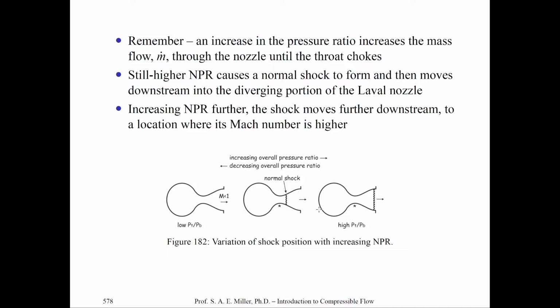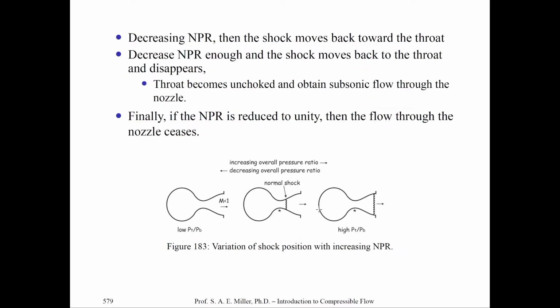And this is strange because now the shock waves will exist outside the nozzle exhaust until some particular position called the on-design position, which is only dependent on the area ratio and the Mach number. High pressure ratios, of course, will cause shock cell structures, which we'll show in a bit in this class, to form outside the nozzle exhaust.